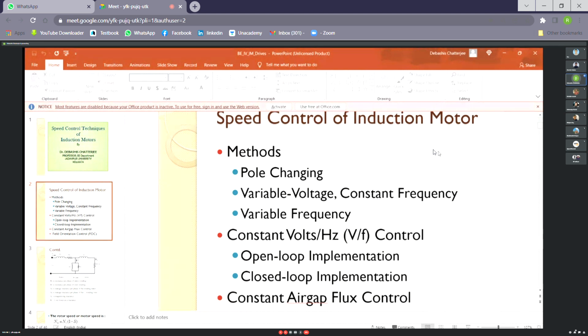So naturally rotor currents will flow. Now when rotor current starts flowing, the rotor also generates its own magnetic field. The interaction of the rotor and the stator magnetic field results in rotation.